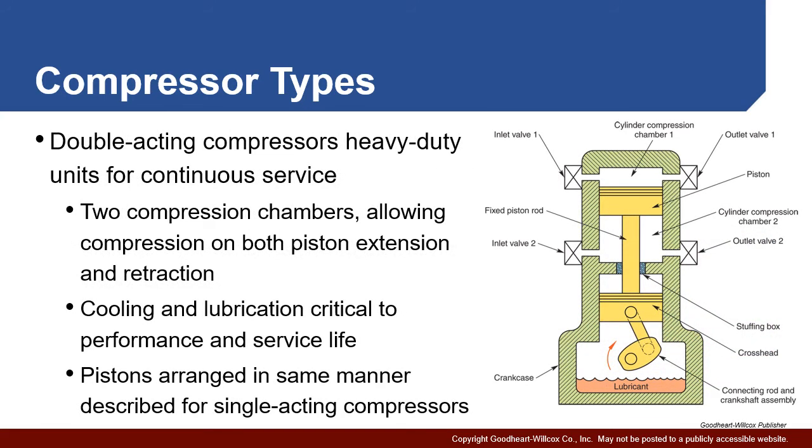Double acting compressors, on the other hand, essentially work in both directions. And if you take a look here, we have a cylinder compression chamber above. We also have one below. As this cylinder goes up and down, the compression stroke of the upper cylinder is actually the intake stroke of the bottom cylinder, and vice versa. So this is constantly going back and forth, and it's compressing the fluid in both the top and bottom chamber.